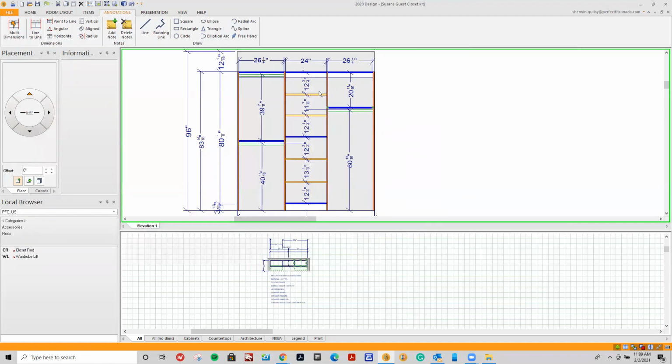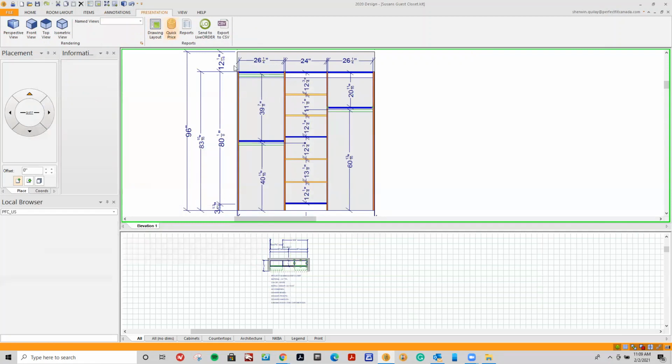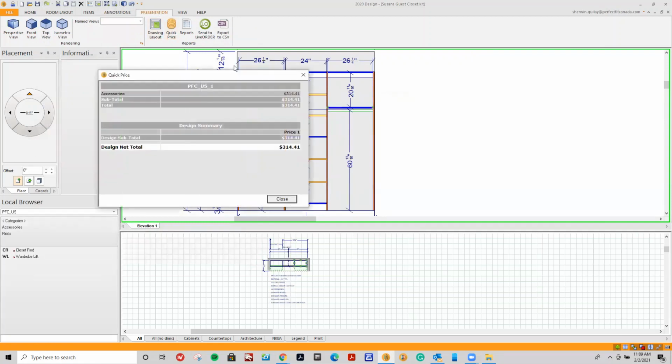Traditionally, I like to make a minimum of 2 fixed points for wall modules and tall modules as my very, very minimum. More fixed shelves are better than less because obviously it adds stability. The boards are very long already, so you want to make sure that you have fixed shelves in the middle wherever you can.